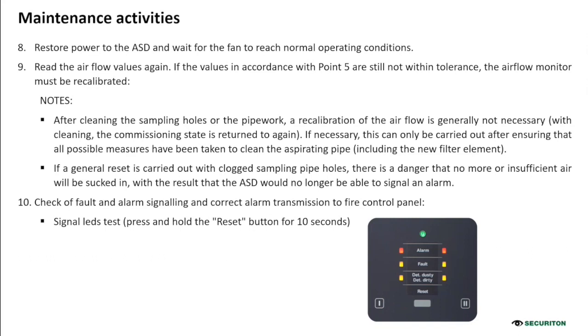Also, in the question there was somebody who asked about the necessity to clean up the airflow sensor. In this case, if you see that after all the maintenance the value is not rising to 100%, you can check the airflow sensor, and then after that, you can make the initial reset.